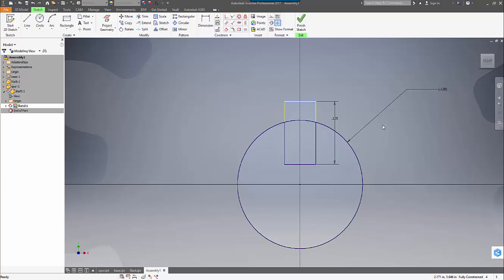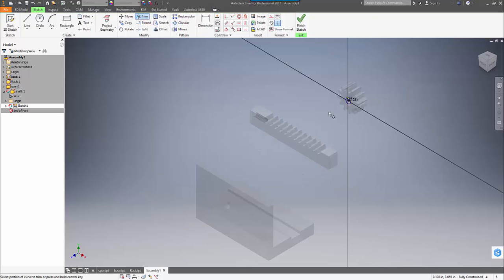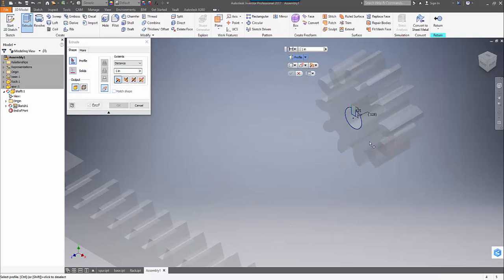Okay, so now at this point, I need to trim this top part out because it's part of the circle that I don't need, but I do need to now extrude this. And we're going to need to extrude this particular object. We'll extrude it 3.5 inches. So we'll finish the sketch, choose extrude. It doesn't know exactly what to extrude, so I'll select the object to extrude, which is the created surface. Now again, if the object does not automatically get selected, you need to select that profile. You need to go and actually select that object.